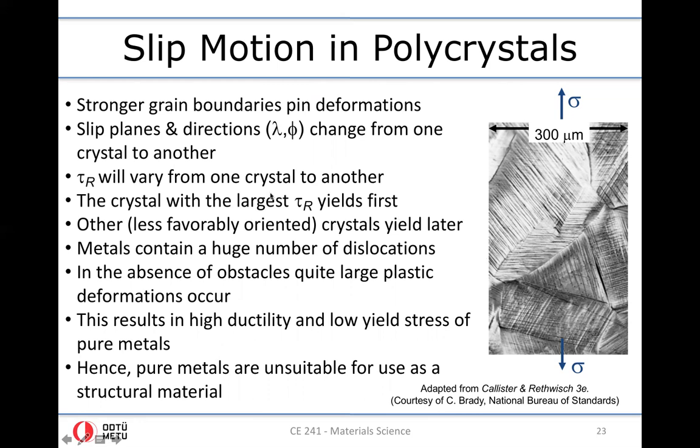And obviously, when you subject such a polycrystalline material to uniaxial loading, the crystal with the largest resolved shear stress would yield first, if you assume that the critical resolved shear stress is the same for all these crystals, assuming that the crystals are of the same kind but with different orientations. Others, in other words the ones that are less favorably oriented, yield later.